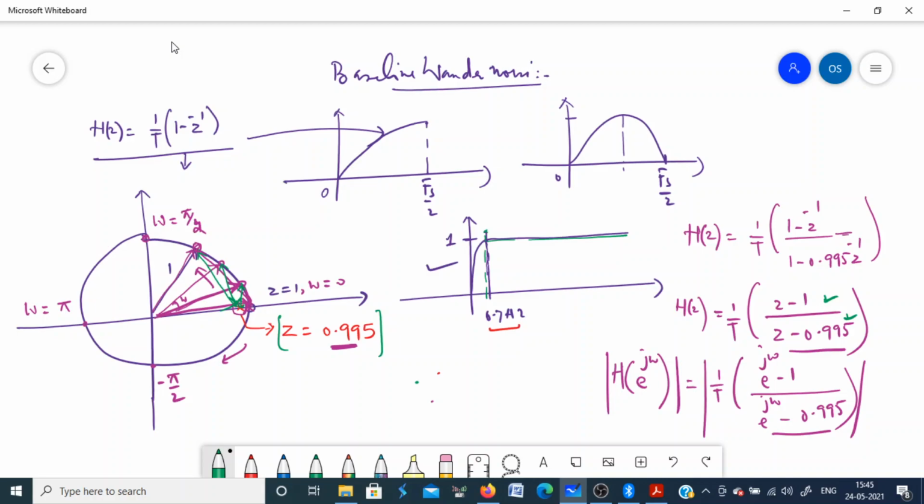Or more generally in DSP, when we use filters for removal of low frequency artifacts, we generally use a FIR filter. You can also design like that. A FIR high pass filter you have to use with a cutoff frequency of 0.7 Hz. So you may design it using a window method. That we already know.